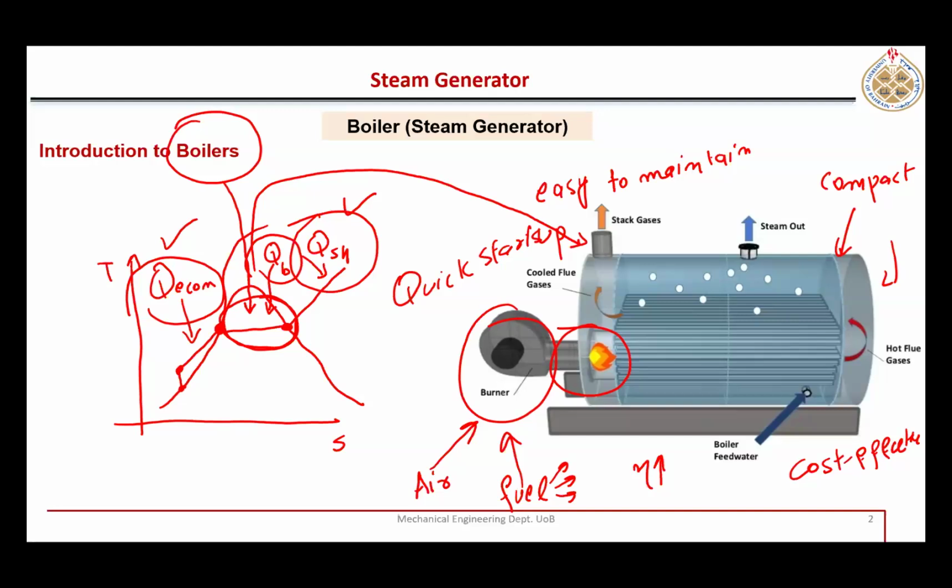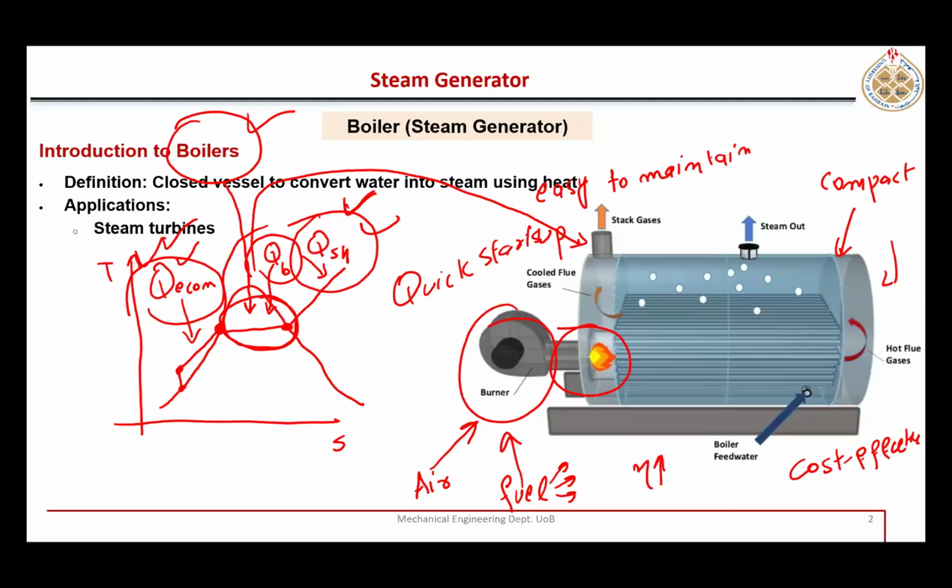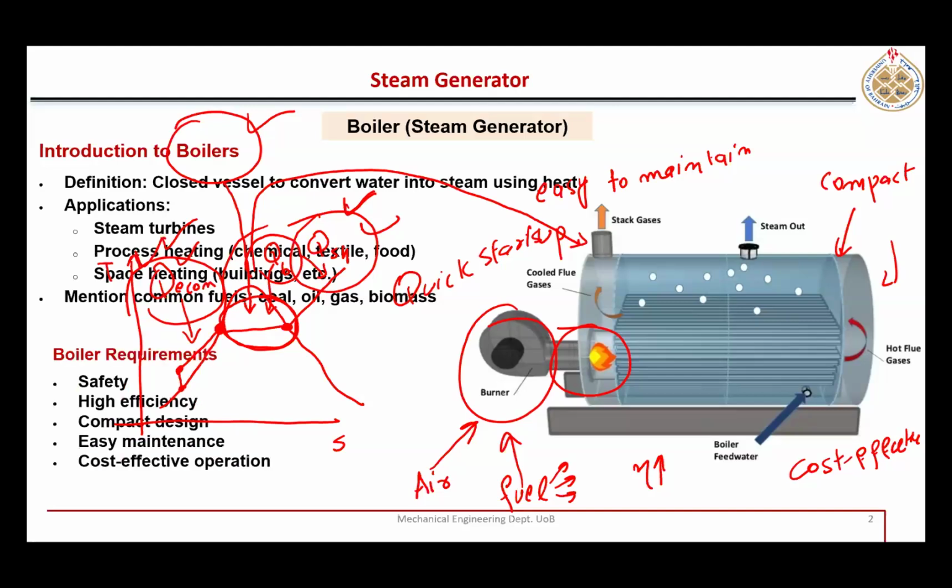So a boiler does not require an economizer or superheater to function. These two, economizer and superheaters, are just performance enhancing accessories. They are installed normally externally or integrated in new advanced boilers, but they are not a part of the fundamental definition of that boiler. Those do not include this economizer and superheater. Okay, so this is just the simple theory.